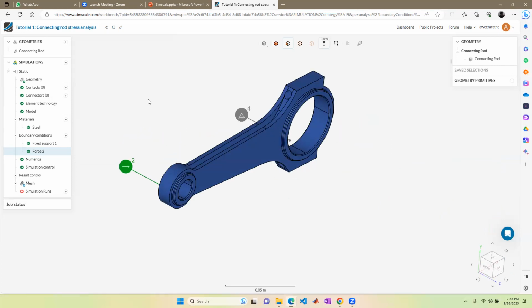Now once again, you have to go through your problem definition in your head and figure out whether you have applied all the necessary boundary conditions. As a practice, I do this every time I add or remove a boundary condition, since this particular area is where you're most prone to make a mistake. Right. So let's go to the definition once again. We are keeping a certain set of faces fixed, applying a force on another set of faces, and we need to find the deformation and the displacements within this body.